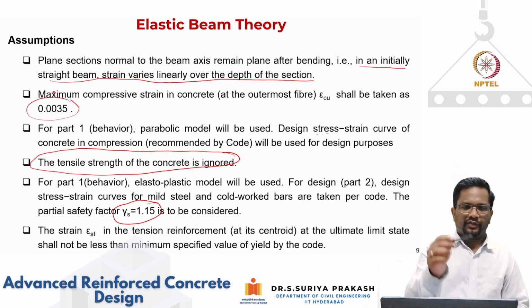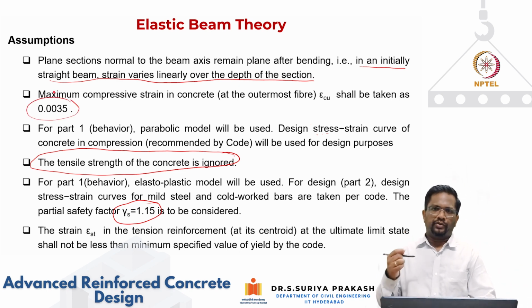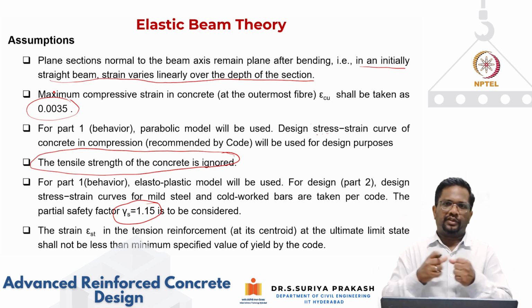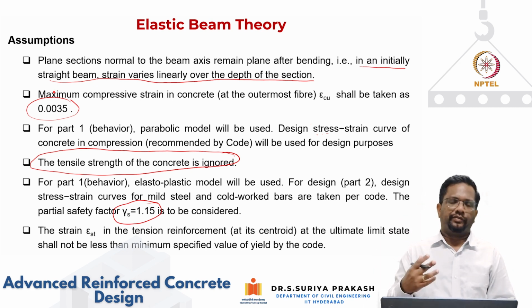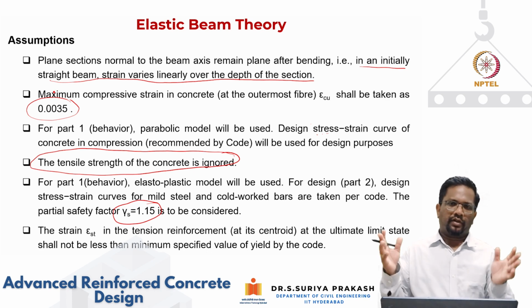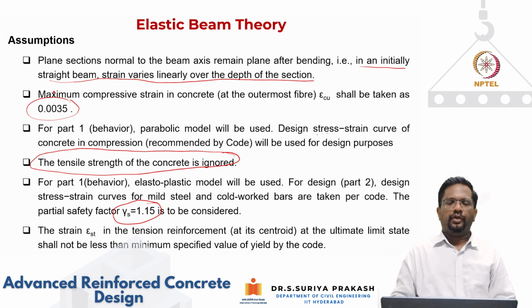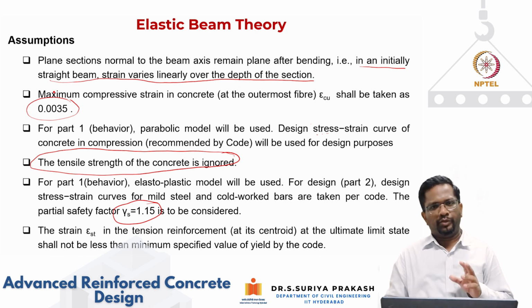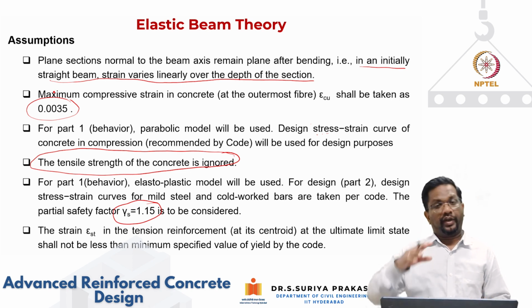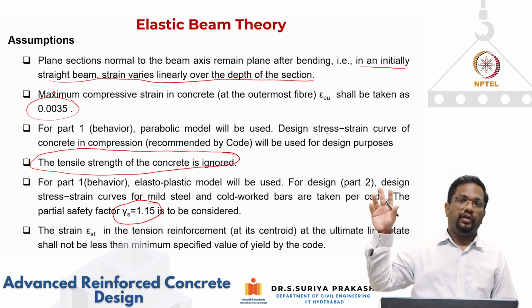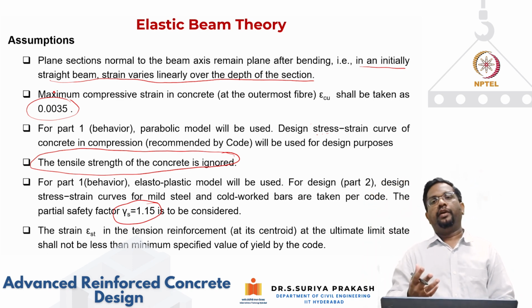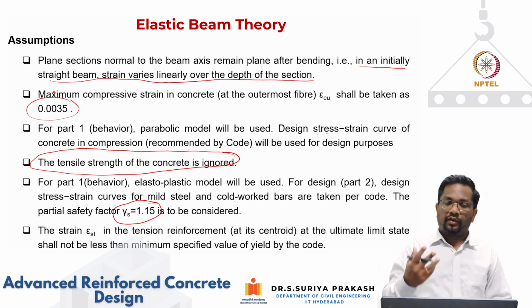As we have seen in the previous material module also, you may remember that when concrete fails in compression, it's a complete destructive failure. The material undergoes complete disintegration. So we have to be careful. We don't want concrete to reach its failure strain before the steel does. Finally, if I'm testing some beams in flexure, the final failure will be by concrete failing in compression.